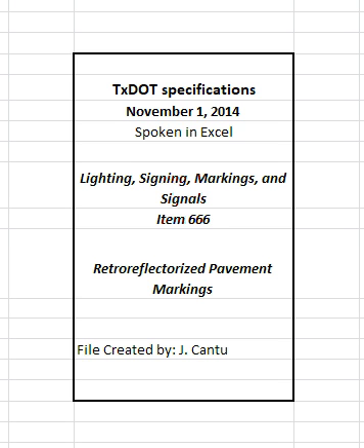4.5.3 Traffic Control. Provide traffic control, as required, when taking retroreflectivity measurements after marking application. On low-volume roadways, as defined on the plans, refer to the figure, Temporary Road Closure in Part 6 of the Texas Manual on Uniform Traffic Control Devices for the minimum traffic control requirements. For all other roadways, the minimum traffic control requirements will be as shown on the Traffic Control Plan, TCP, Standard Sheets TCP 3:1 and TCP 3:2.